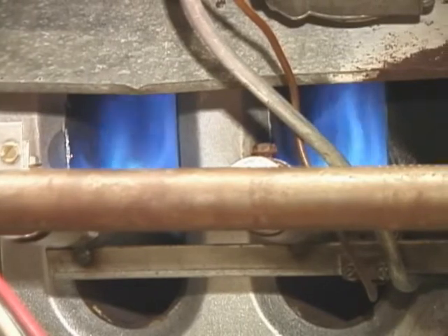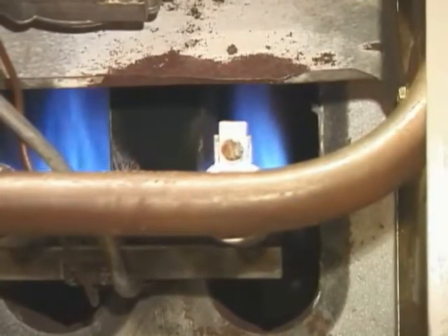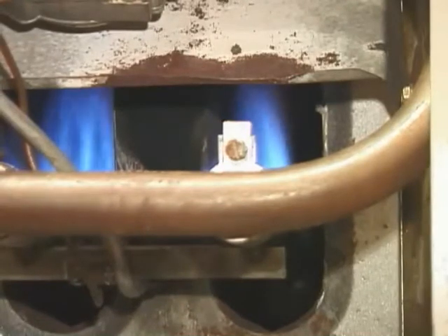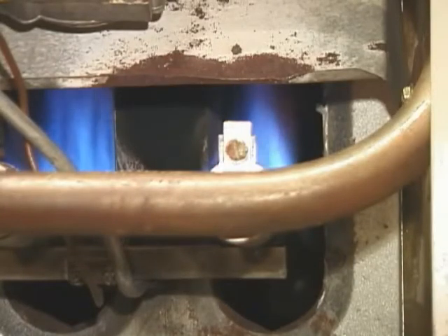Therefore, in addition to removing the combustion byproducts from the building, proper venting is also critical for complete combustion to occur in the first place. If too much or too little combustion air is provided, this can negatively affect combustion and hence the efficiency of the system. For all these reasons, testing draft pressure in all Category 1 appliances is imperative and is a fundamental part of a complete combustion safety testing protocol.